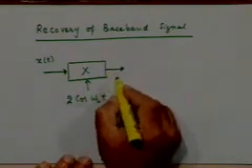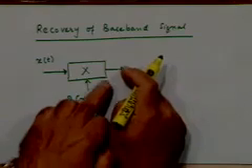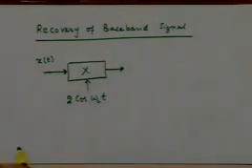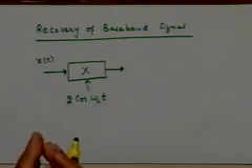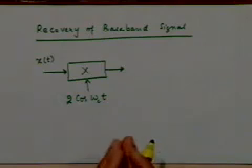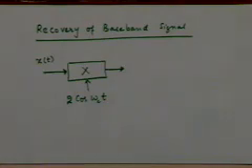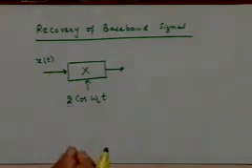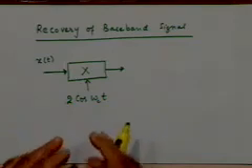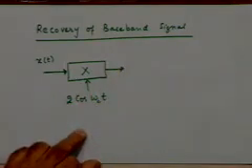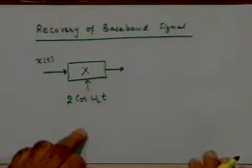Now what will this do? What will be the spectrum that you will see here? As we saw in the case of modulation, the message waveform spectrum gets translated up by fc and also down by minus fc, right. That's what happens. The same thing will happen to x(t). So the spectrum of x(t) would, after multiplication with 2 cosine omega ct, translate to a component around 2fc and also 0.